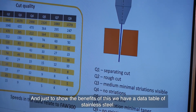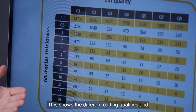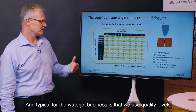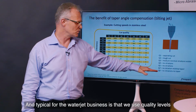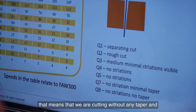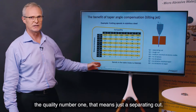And just to show the benefit of this, we have a data table of stainless steel. This shows the different cutting qualities and the speed at different material thicknesses. And typical for the waterjet business is that we use quality levels for describing different quality of the cut surface. The quality level number 9 means that we are cutting without any taper. And quality number 1 means just a separating cut.